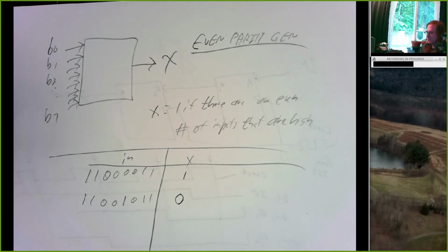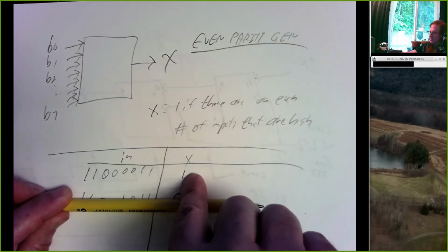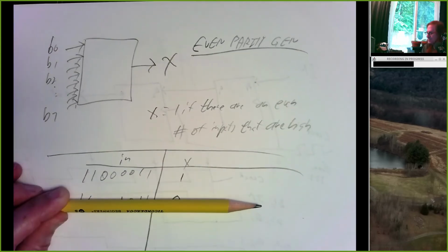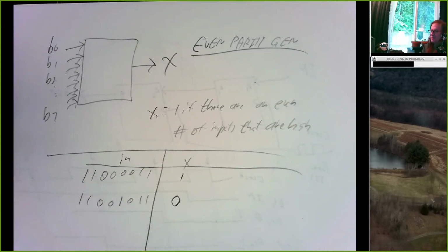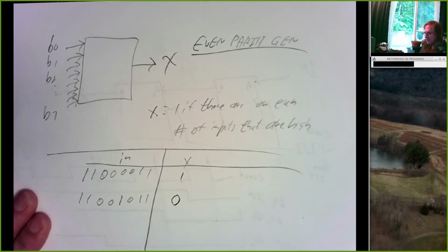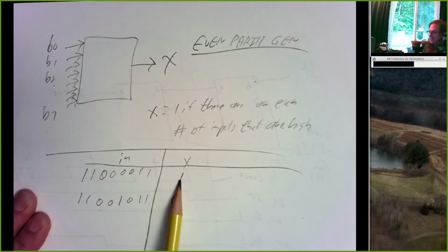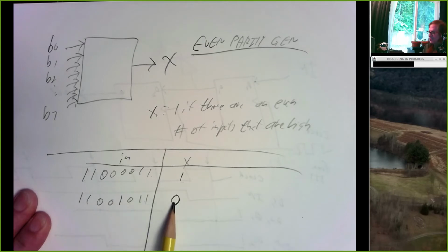And if we're sending information from one machine to another, instead of sending just 8 bits per character, right, if we're using like ASCII code, we send 9 bits. And we add this 9th bit using a circuit like this. And whenever we receive this 9-bit packet of information, we can count how many 1s we have, including this. And the result in this case should always be odd. If we had an even number of 1s in here, we're going to add another 1, which will make the total odd. If we had an odd number of 1s in here, this will be a 0.